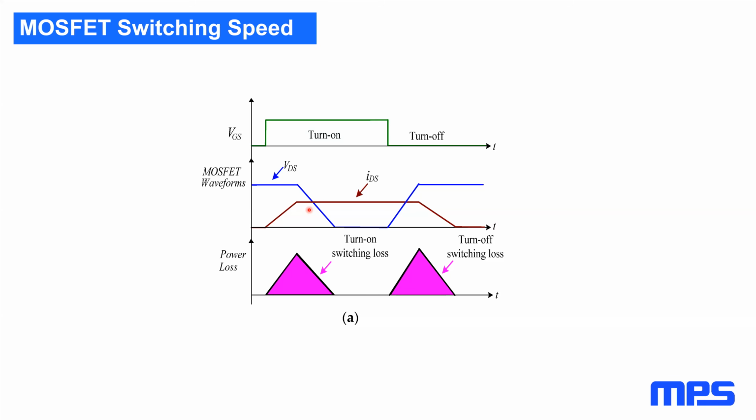A lot of customers who are using high currents like 100 amps in battery-powered tools, for example, actually go for 100% margin. So if it's a 12-volt battery, they'll use at least a 24-volt MOSFET. It depends on the load current. If the load current is low and you have a well-controlled power supply, you don't need that much, but you do want margin. And the current is usually more of an issue about power dissipation. So it's RDS on more than the current of the motor.